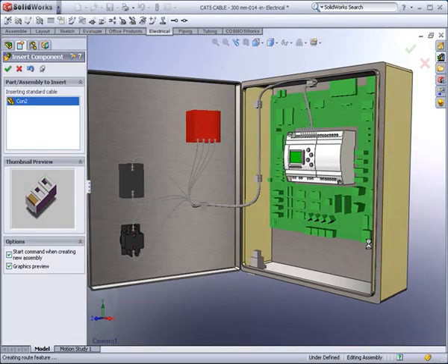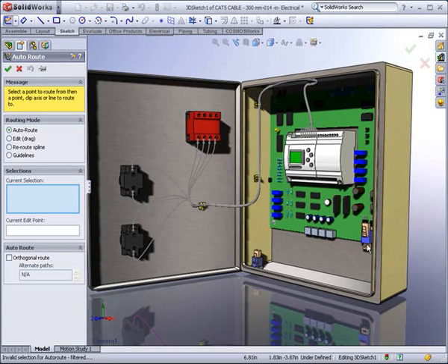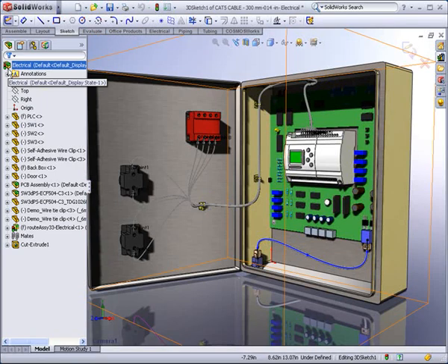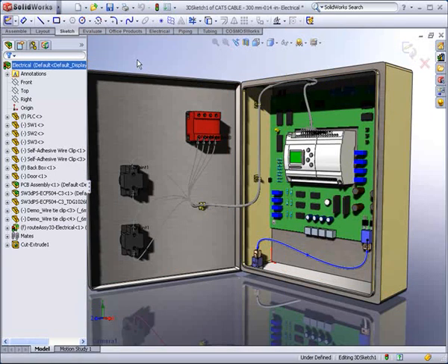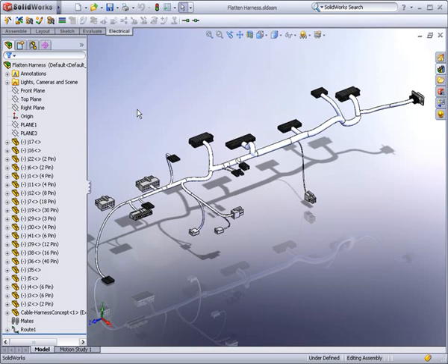Another benefit of using electrical routing in SolidWorks is the ability to automatically flatten a 3D harness and then create a harness drawing. With SolidWorks, you can detail a harness in an engineering drawing that conveys all the information required for manufacturing. Here is a harness assembly in 3D. This 3D view is great for understanding where the connectors will sit in 3D.